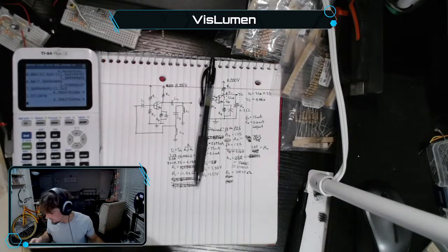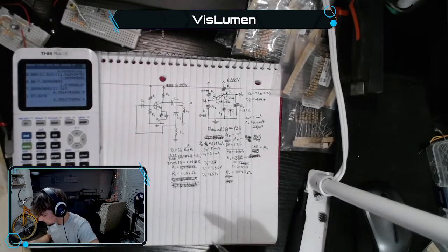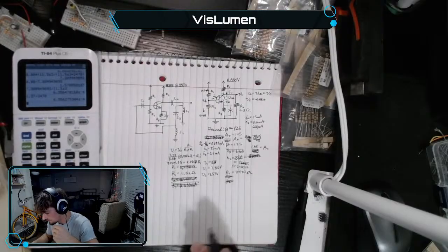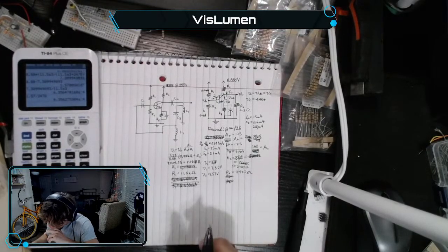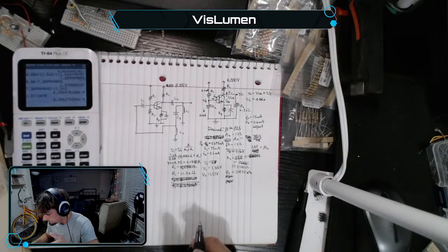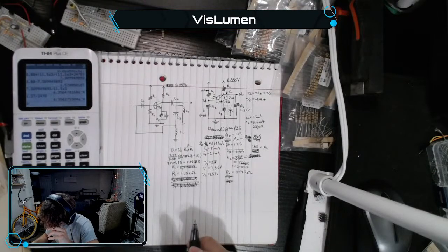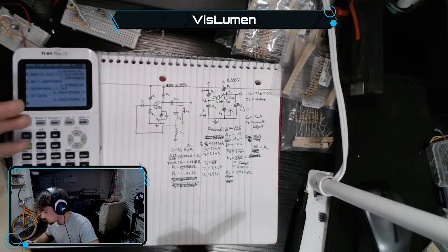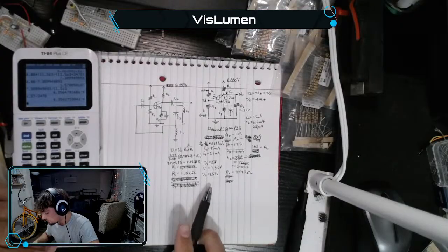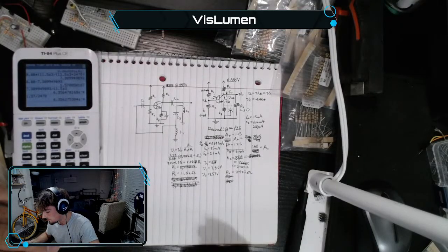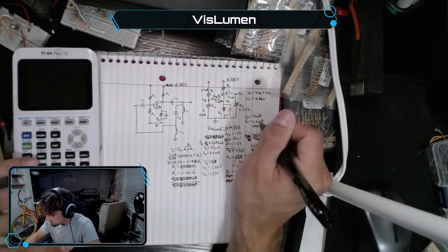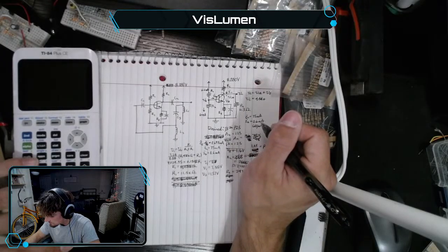Man, I do want to make it work though. That is absolutely true. I want to see it work. I want to record it with the oscilloscope and see the frequency that we've established. So to get this amplifier working, what else? RC. In order to know AV, yeah, we're going to have to do the small signal analysis. But this is what we want to shoot for. We want to shoot for the gain of 125. Now, in regards to IC equals beta, yeah, we know IC is 75 milliamps. So what is this going to tell us?